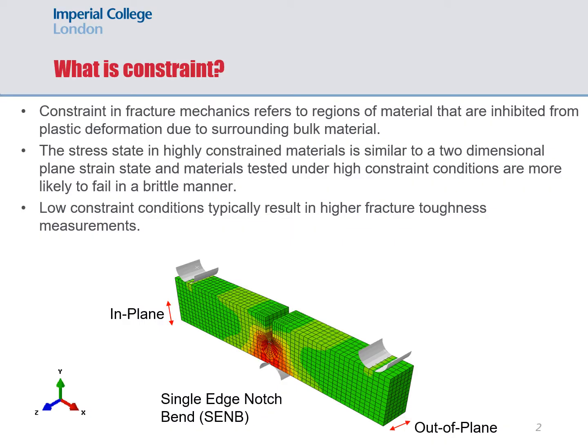Structural integrity assessments conducted using fracture mechanics are used to determine the operational life of a component. Generally, we're concerned with preventing catastrophic failures like those associated with brittle fracture. Components manufactured from materials with low toughness will invariably have shorter operational lives compared to high toughness material. That's because fracture toughness is considered a key parameter in a structural integrity assessment.